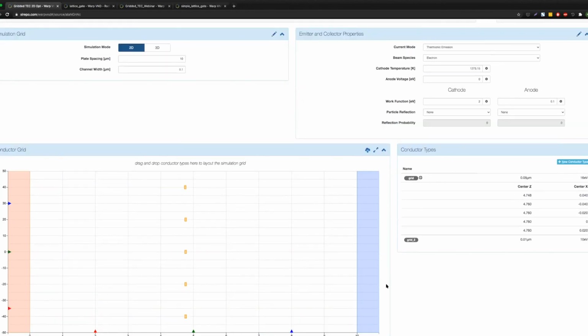So Michael Campanelle asked a question. I'm wondering, for offsetting the space charge effect, how is inserting a mesh in the gap advantageous over moving the anode closer to the cathode? Yes, so in general, it's not advantageous. In theory, it's not advantageous. In practice, it's very difficult to make these gaps much smaller than, say, 50 microns.